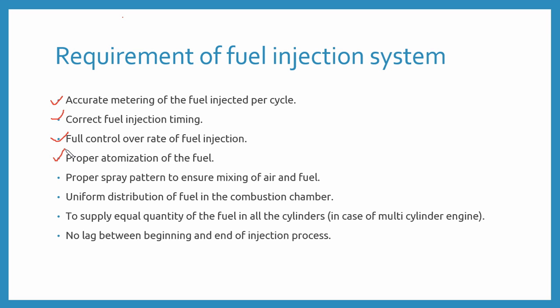We need proper atomization, which means it needs to be sprayed through a nozzle in such a way that when it comes in contact with the compressed air, it ignites. For that reason we need to atomize the fuel in a proper way. Next is the proper spray pattern to ensure the mixing of the air and fuel.